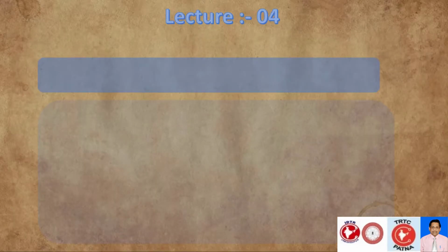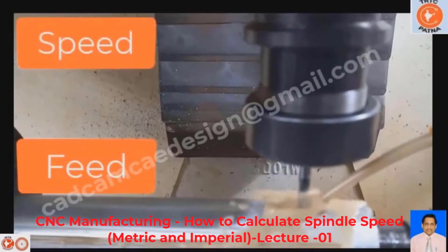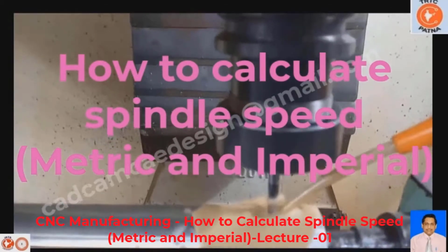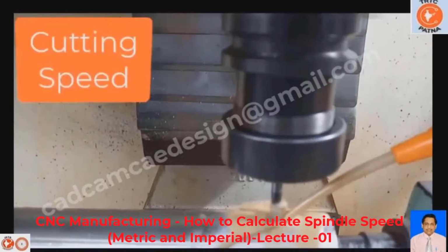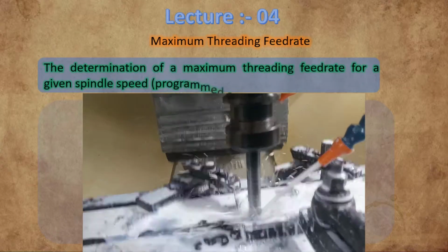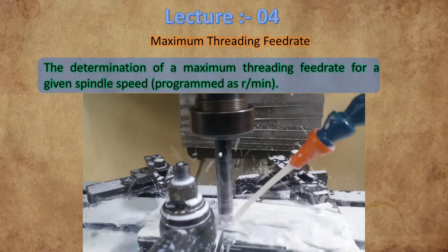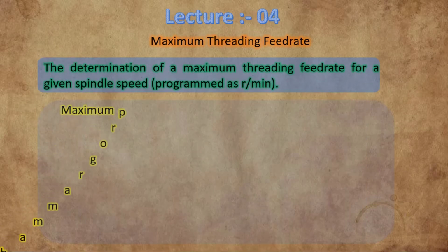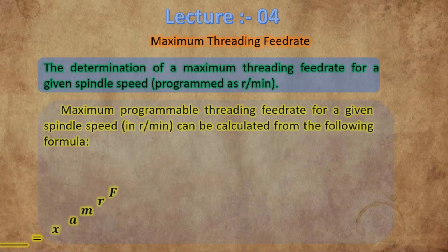Now the next topic is the maximum threading feed rate. The selection of cutting feed rate in general was discussed earlier. After studying the section on maximum revolution per minute selection, and spindle speed, already discussed in my first lecture on how to calculate a spindle speed, it should not be surprising that similar limitations apply to the determination of a maximum threading feed rate for a given spindle speed programmed in revolutions per minute. Again, the limits of the CNC machine tool are very important, so be aware of them when writing the thread cutting program.